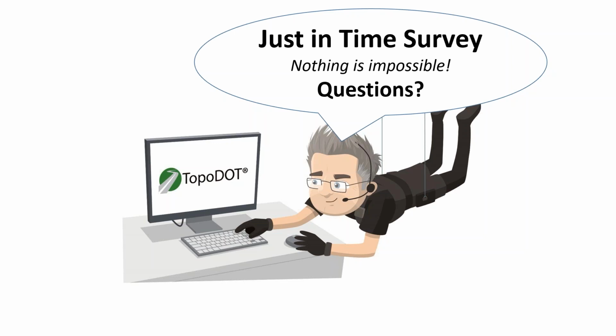We've had some questions, and I've been answering them in text form. Philip Carrier asks if 3D modeling works on PowerDraft with TopoDOT. Yes, TopoDOT works in PowerDraft. Topo Cloud works in PowerDraft. PowerDraft does have some 3D functionality. Some of it is stunted, like creating meshes and creating solids. But everything in TopoDOT that we do is basically extracting break lines, 3D break lines, 3D spatial shots, and all that is available in PowerDraft.